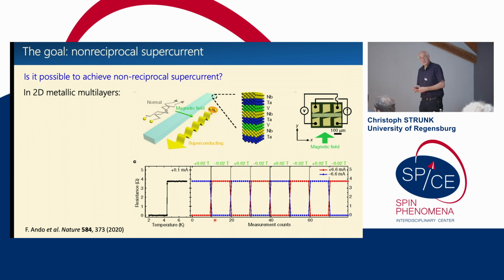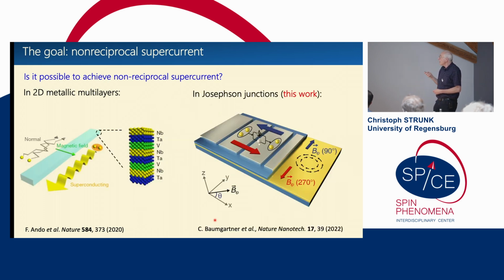So this occurs if you have, say, a positive and a negative critical current which are different, and where you bias with a current exactly between these 2. That is what they did here in this picture. When this paper came out, we measured our device, which is here the chain of Josephson junctions, and found a very similar phenomenology, although for very different reasons.